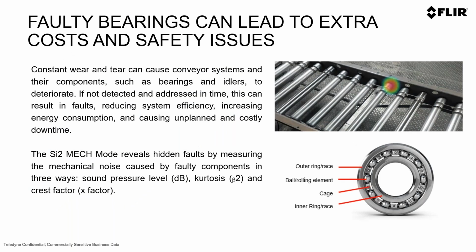Basically, mechanical fault detection finds varying faults. This is a very common failure or issue that some facilities have. Constant wear and tear can affect the conveyor system and its components such as bearings and idlers. This can deteriorate for different types of reasons. And basically we are detecting and addressing them to spot and identify the location where these components